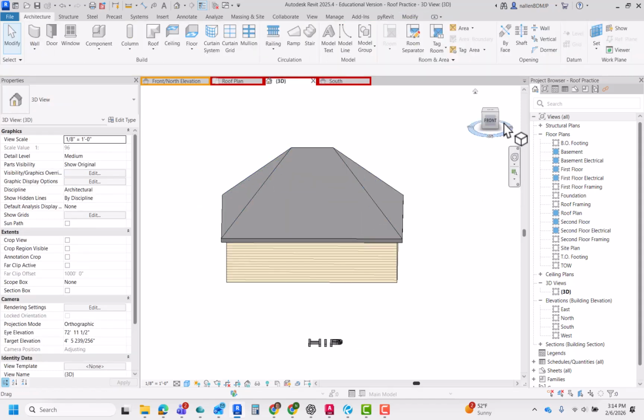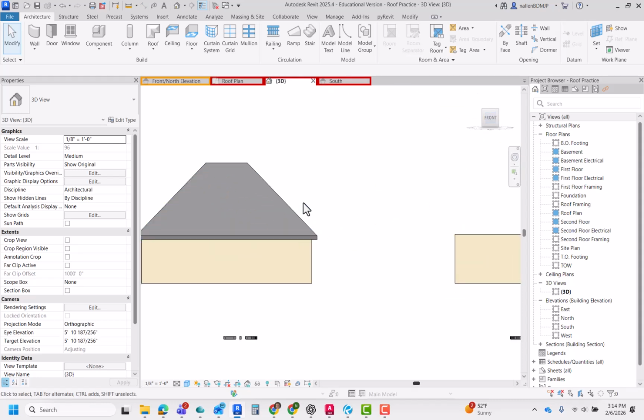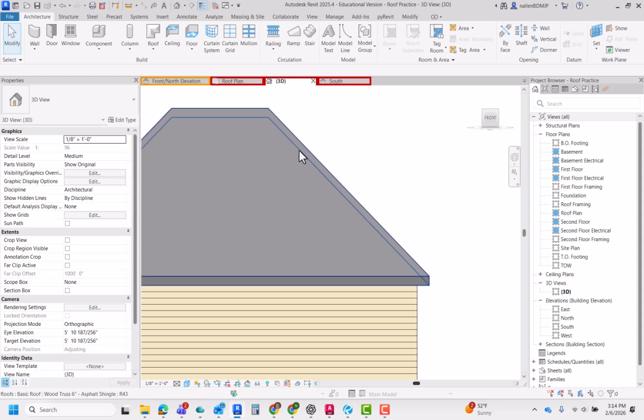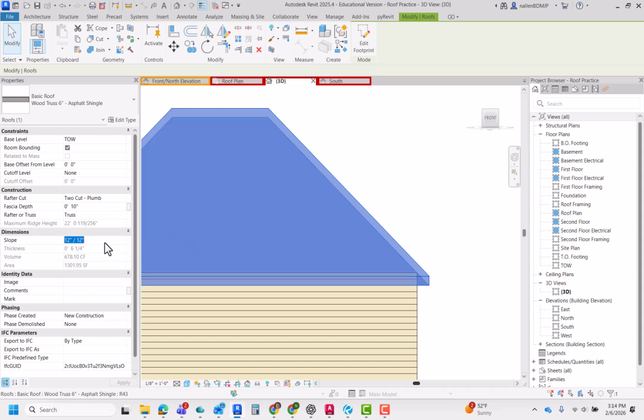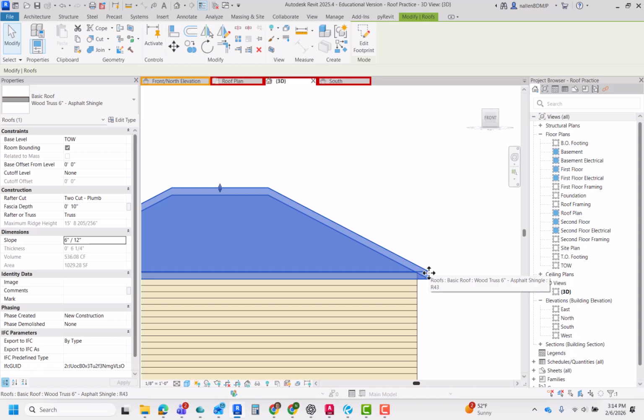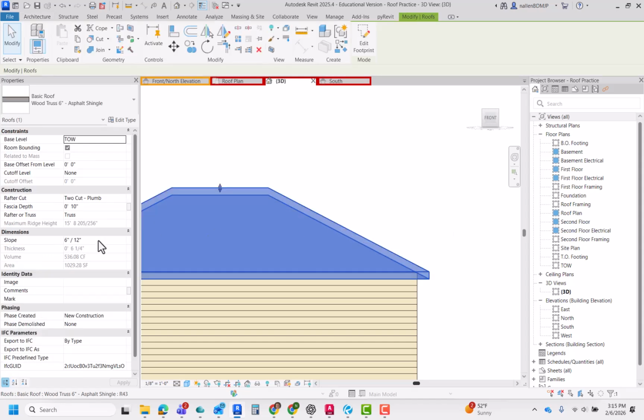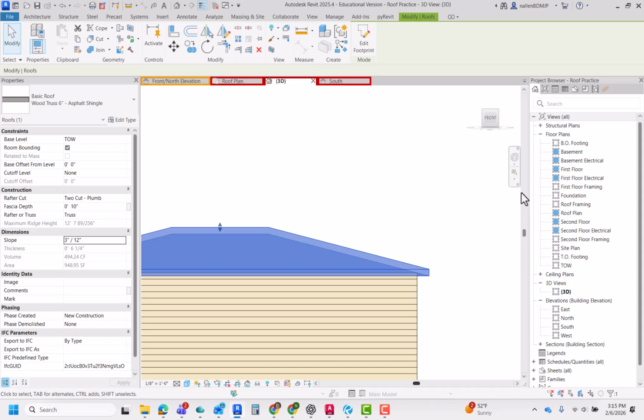12/12 is interesting because it helps us understand slope the best, I think. When we're talking about slope, what we mean is for every 1 foot or 12 inches this direction, we're going to go 12 inches vertically, which means that a 12/12 gives you a perfect 45-degree angle. We're going over 12, up 12. When I go with something half that, it would be a 6/12. That would mean that for every foot we go over, we're only going to go up 6 inches. So this is exactly half of a 45-degree slope. Okay, and then all the other numbers are just somewhere in between. Go down as low as 3, or back to 9 where we started.